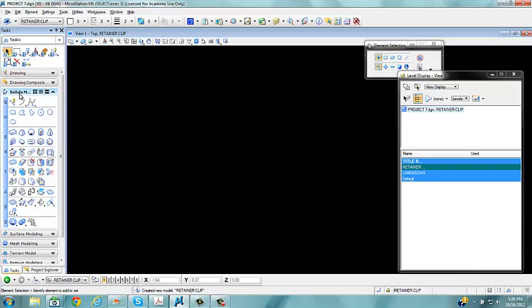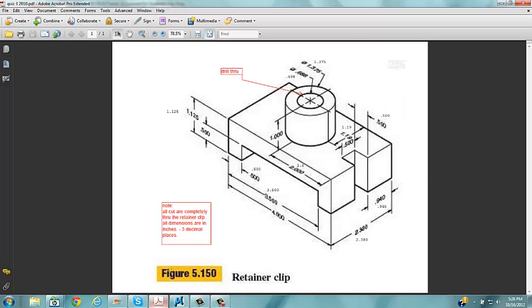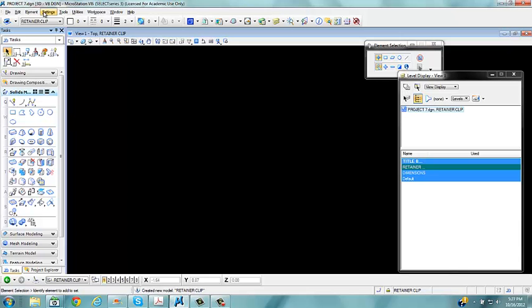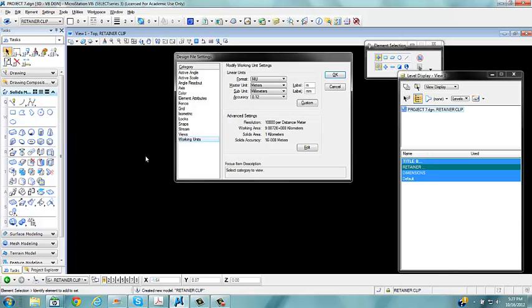And we're going to use our solids modeling tool, starting out with, if we look at this again, an overall 4 foot by 2.380 by 1.125, just to get a box in there. Go settings, design file, make sure our working units, this one's in meters, we want to make sure it's in inches to 3 decimal places. We'll say OK.